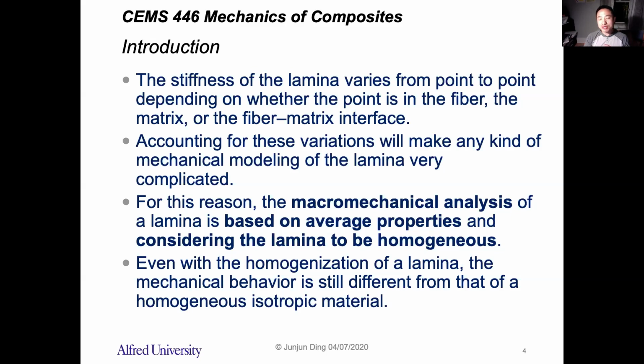And if you want to have a model to calculate that many fibers and matrix in the laminate, the calculation model will be extremely hard to run, because you have to deal with those independent fibers, and each fiber has its behavior under the mechanical loading.